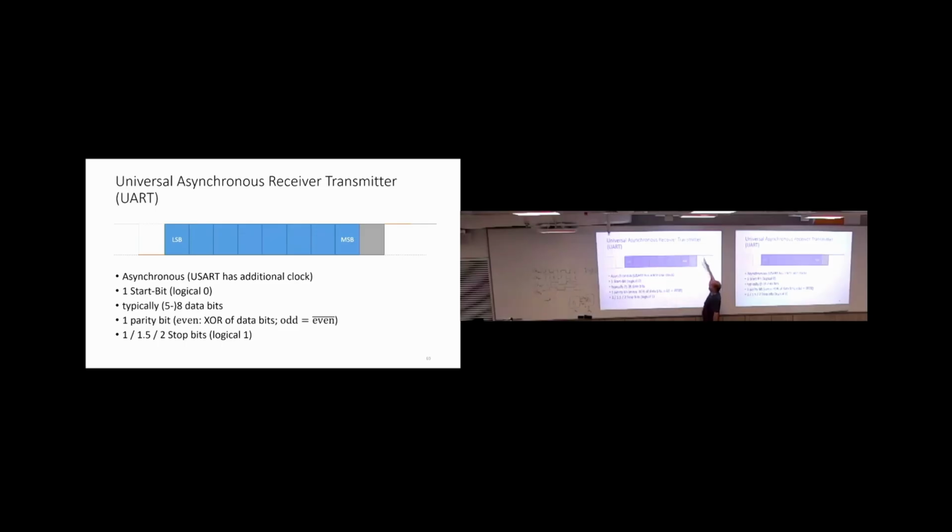That's effectively this one here. So, that means if you look into your wire and you observe it, it's driven to 1 all the time. And if a message starts, it's pulled to 0. Then some bit sequence follows, and then if it goes back to 1, you know the word has ended.